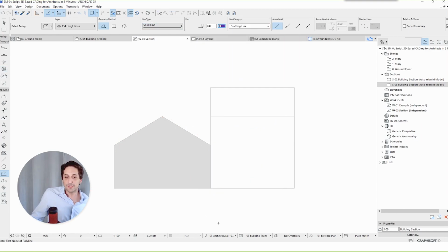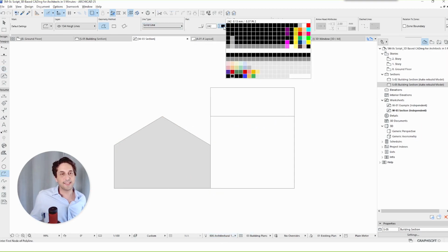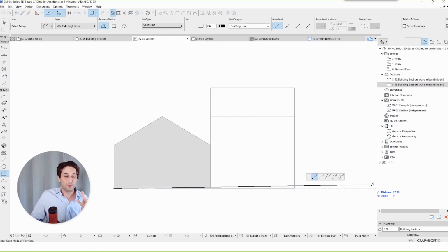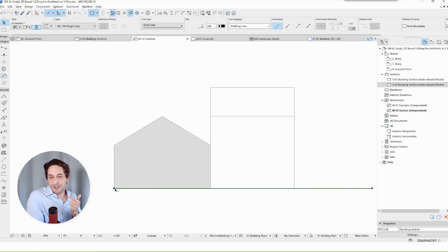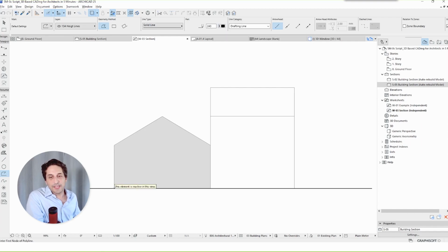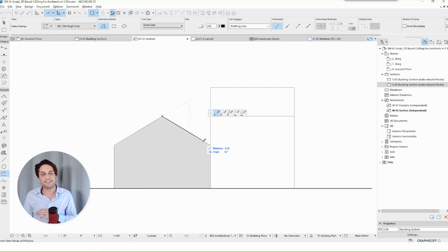Now we can start the polyline tool and trace a section. Then we start changing only the settings that we need, because we're in ArchiCAD, so you always need to change the settings. Let's go and trace the cut building with the second thickest line, which in this case is 243. You can then use the offset to add thickness to your building.